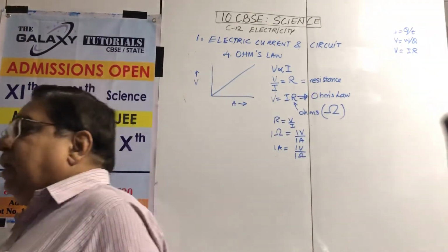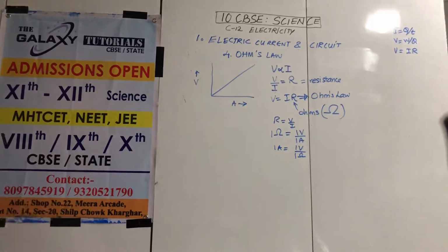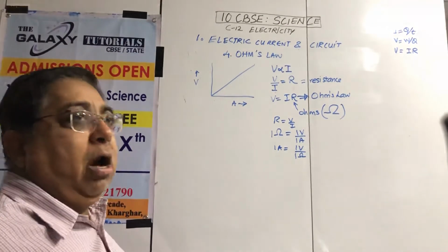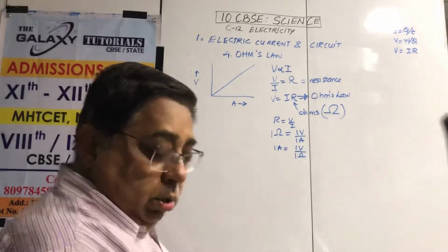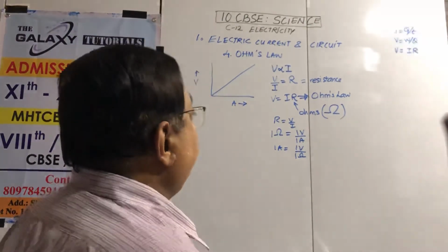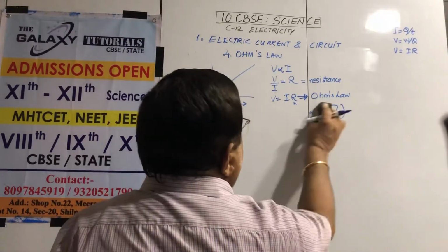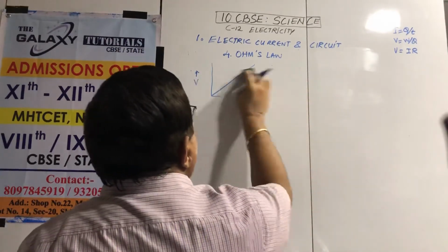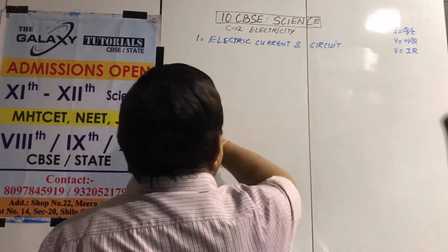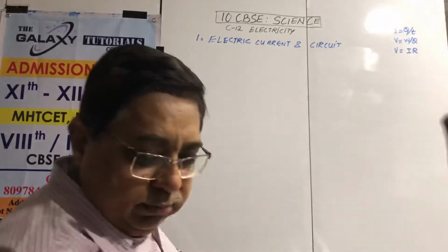The problem with aluminium wires is it is a good conductor, but it is brittle. If you bend aluminium 2-3 times, it will break. Copper is quite malleable, so you can bend it in the house circuits, etc. They have never broken much unless they are impure. So we will have to know the material you are giving me. Now you will say use iron. Iron conduction is low, resistance is high, but it is the cheapest.